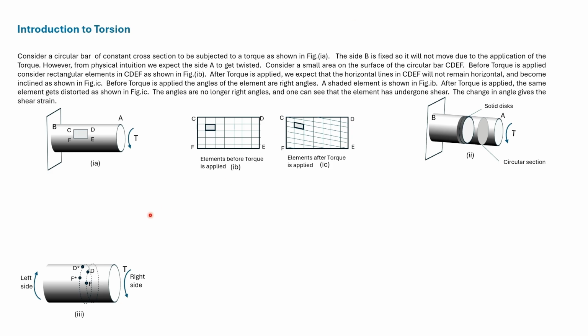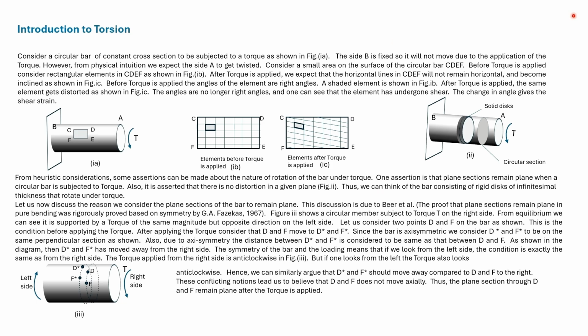They stay in the same circular section. Hence, we can say that the plane of which the points D and F are a part remains plane after the torque has been applied. Hence, our assertion that plane sections remain plane.